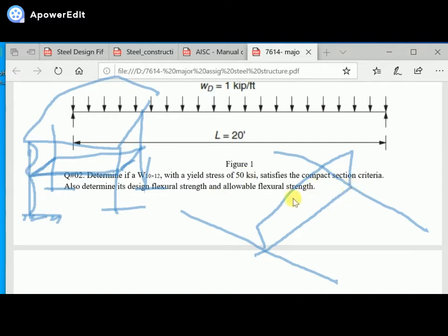For example, let us come to the beam. You see here, if we provide some lateral beams to this main beam, now the behavior of this beam will change. Before these lateral beams, for example, the beam will bend in downward direction, as well as it will buckle in this direction, or it may buckle in that direction, basically.